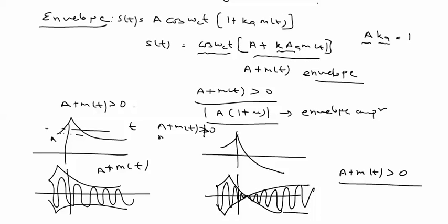There is some phase reversal due to negation of the magnitude. Due to the negative sign, cos is multiplied with a negative quantity. Magnitude is not affected, but the phase of the carrier is changed. Cos omega c t is now phase reversed due to negation in the magnitude.